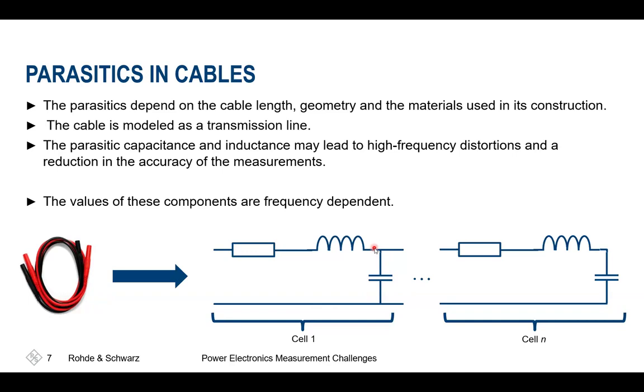And typically today, we recommend to use only high quality connector cables because otherwise, if they're too cheap or maybe sometimes too old, the copper is not that clean. You'll have higher losses and you'll have a high effect on your measurement caused just by these parasitics inside the cabling itself.